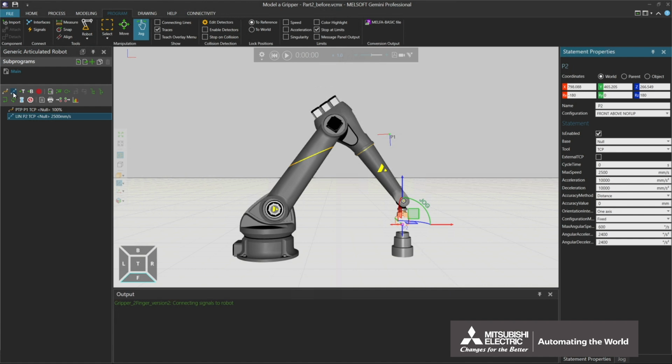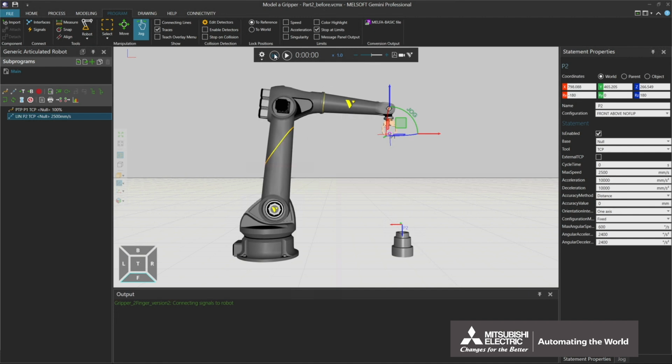Set the open or close motion of the claw to grasp the product as follows. A signal to open or close the claw needs to be sent. Before setting the signal, check what signals are used for the robot tool. Reset the simulation and restore the initial position of the robot.